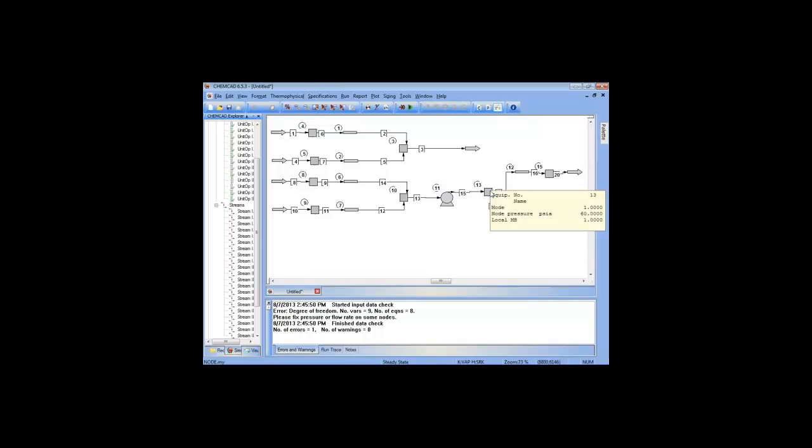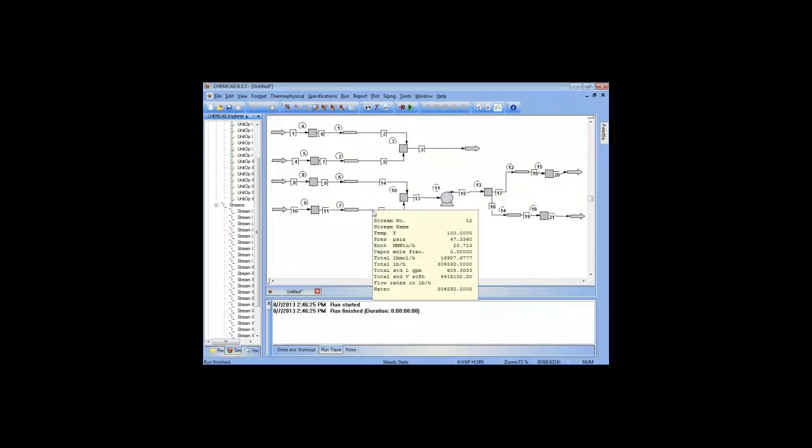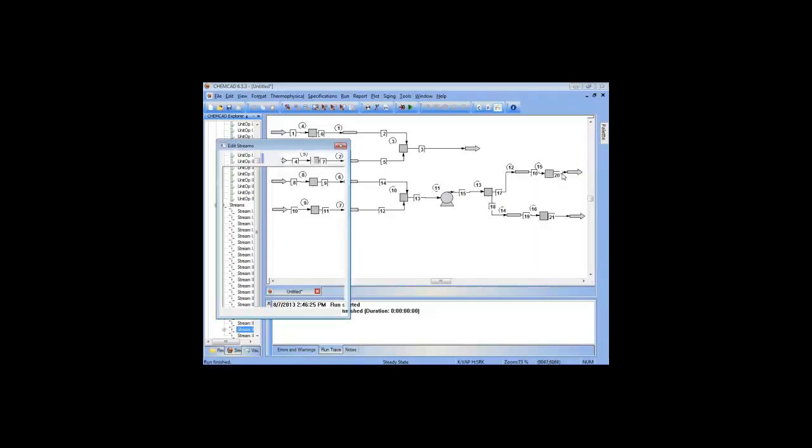So now my 3 settings, because I have 3 degrees I need to set here, one for the flow coming into the network, 2 more for the flows going out of the network, and I have set pressures at each of them. It has worked, 60, and as you could imagine, we need 60 pounds out of the pump in this regard. We've increased the flow some, which back calculated the flow, but we've fixed that. And we still have 50 pounds coming out and 45 pounds coming out.